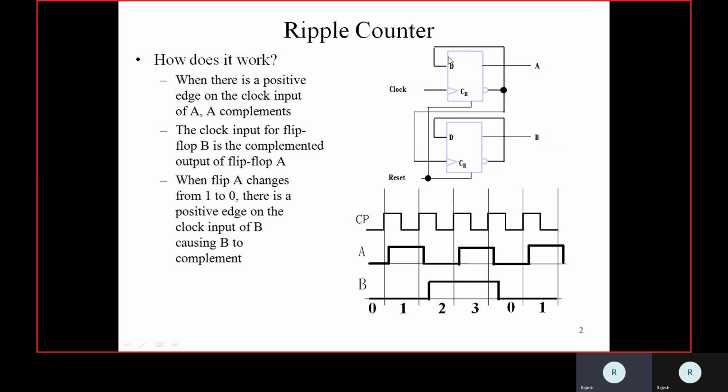because it is a normal D flip-flop implemented as a T flip-flop. So for every clock pulse, the output will toggle relative to the input values. How are we achieving the toggling? By applying A bar as input to the D. You can consider it as a D flip-flop only. The only thing is the input fed to it is the complementary value of the output. So for every clock pulse, the complemented value is fed, so 0 becomes 1 and 1 becomes 0.